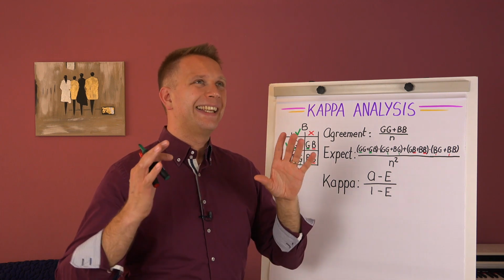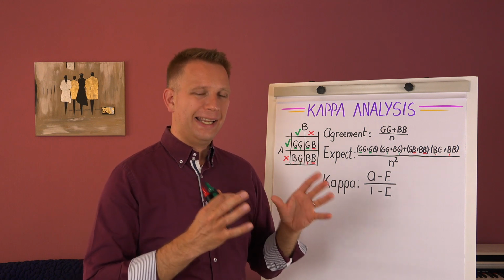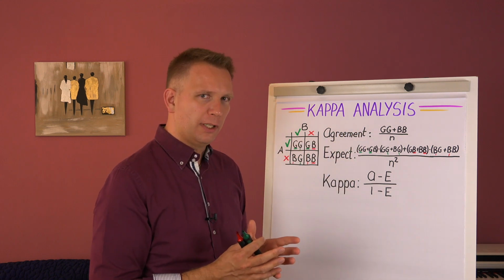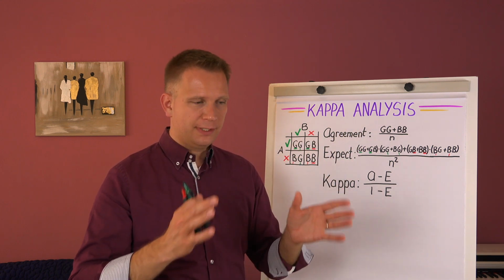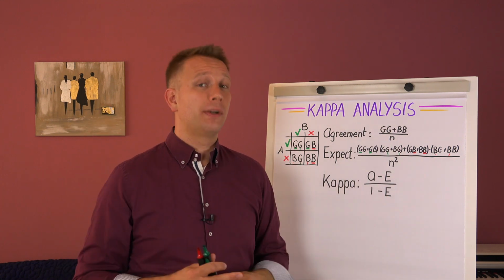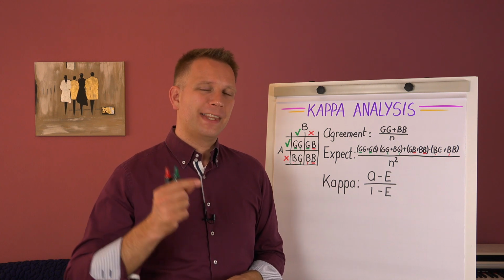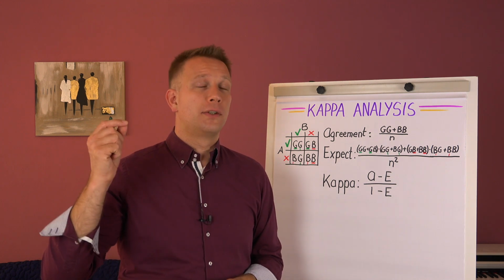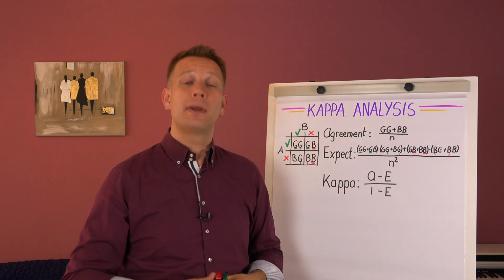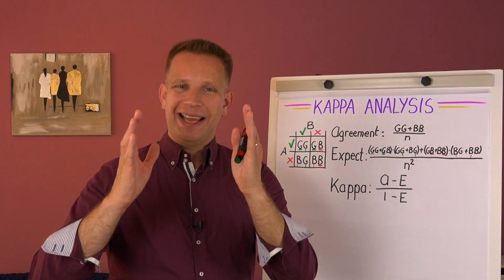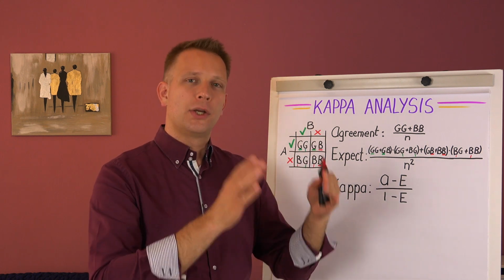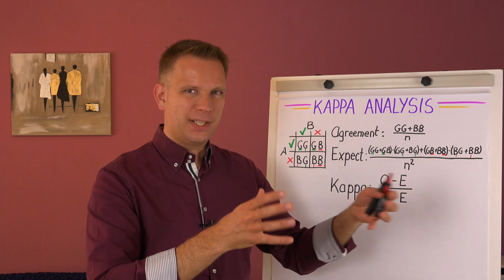Now, there is a different way of calculating it, and it's not a different Kappa, it is a different way of setting up a comparison of pass-fail tests that can handle multiple people and compare all of them together. That is even more involved. There is another way that in practice gives just as good results for you if you're just interested in checking the measurement system. And that is to have a gold standard that you compare each time 1 by 1 your test operators do.